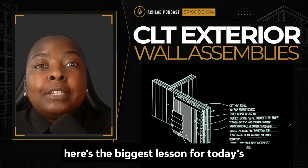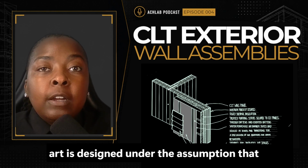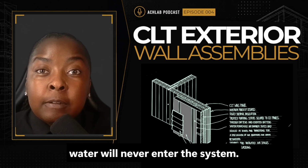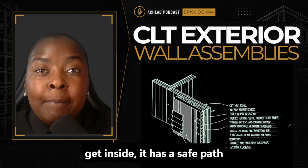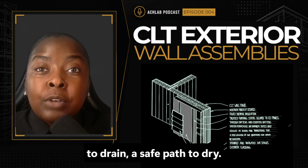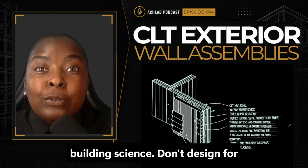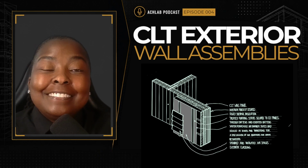And here's the biggest lesson from today's episode. High performance wall assemblies aren't designed under the assumption that water will never enter the system. They're designed so that if moisture does get inside, it has a safe path to drain and a safe path to dry. That's a fundamental principle of building science. Don't design for perfection, design for resilience.